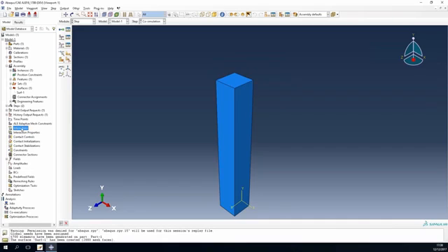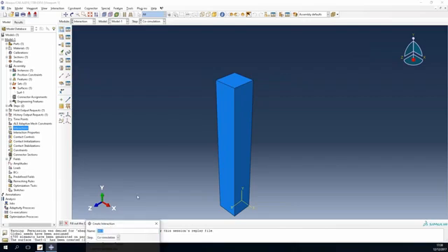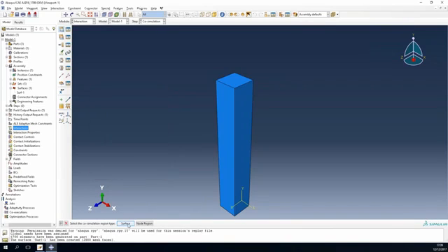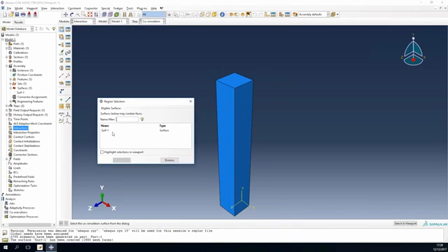The users have to remember we need to create an interaction between the two software, so create an interaction in Abaqus, and we're going to call that a coupling interaction, and it's a standard explicit co-simulation coupling. Okay, so I do that, and of course I'm going to select the surface I created earlier, so my surface 1.